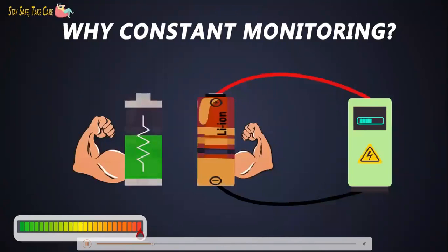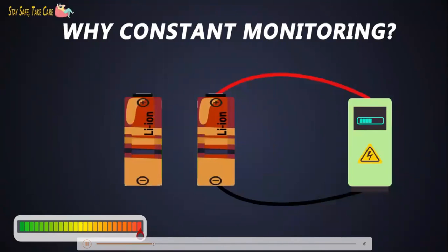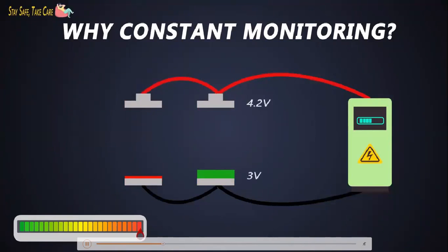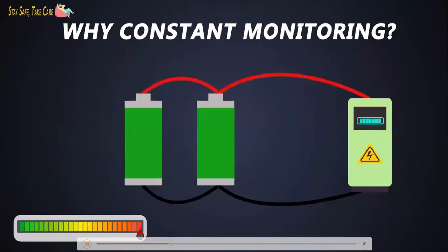Due to the over temperature, the batteries might catch fire. As well, there are always slight differences in the state of charge, charge rate, capacity and impedance between two cells, even if the cells are from the same manufacturer and produced in the same lot. While charging or discharging these cells altogether, some cells experience a lot of stress in the battery pack, so they lead to degradation.